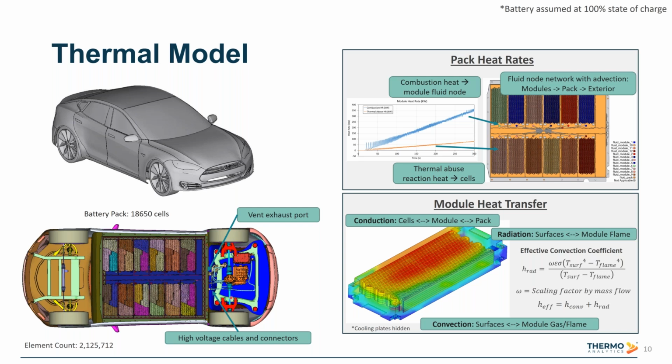And then again, the important thing here with this workflow is that we're not necessarily trying to resolve the propagation physics exactly. Again, you can, but ideally, we're separating these workflows and we're modeling them semi-empirically. Okay, so the most important thing is that we're capturing all of the important heat rates within the pack and the heat transfer mechanisms within the pack.